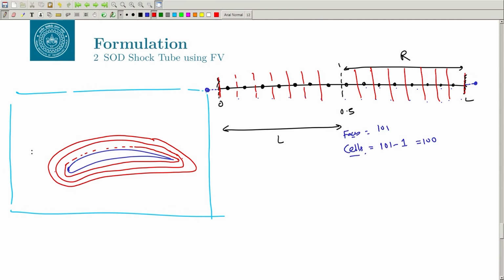Also, let us say you are doing flow over an aerofoil. You can have very nice prism elements, or elements which are close to the body, respecting the boundary layer like this. Then if you go away, let us say this is your domain like this, you can have a very nice grid near the body. Of course, when you go away you have to match to the boundary that you have, so you can put some very nice structured grid here.